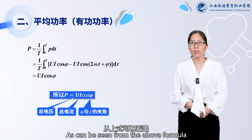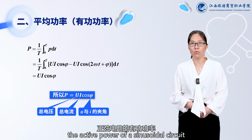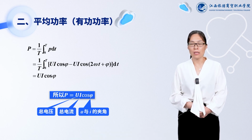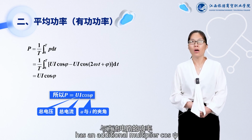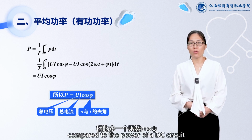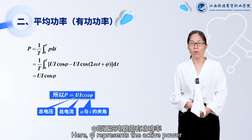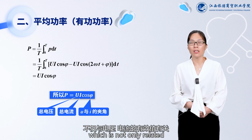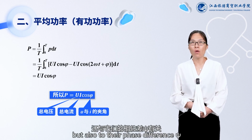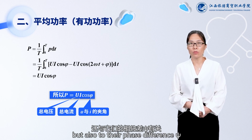As can be seen from the formula, the active power of a sinusoidal circuit has an additional multiplier cos φ compared to the power of a DC circuit. Active power is not only related to the effective values of voltage and current, but also to their phase difference φ.